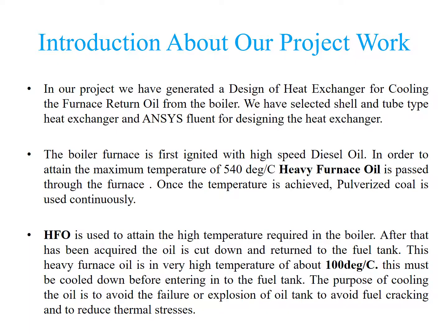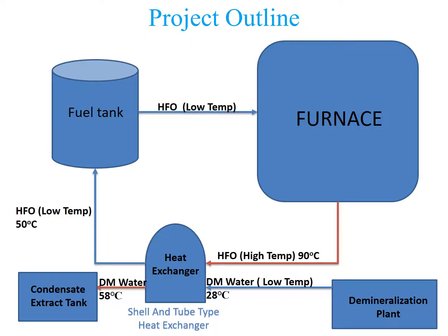This heavy furnace oil is at a very high temperature of about 100 degrees Celsius. This must be cooled down before entering into the fuel tank. The purpose of cooling the oil is to avoid the failure or explosion of oil tank, to avoid fuel cracking, and to reduce thermal stresses.